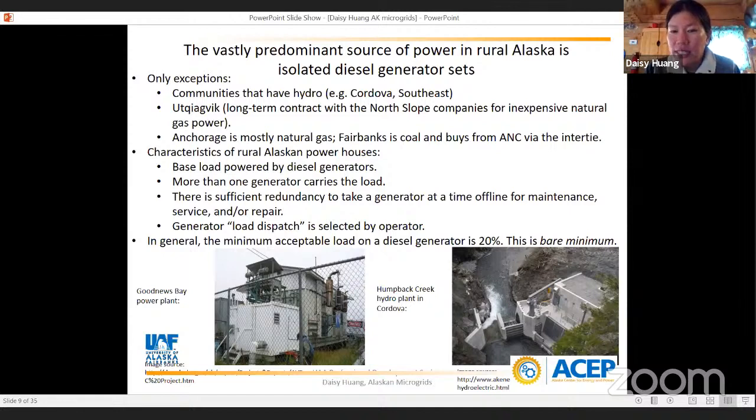Because on a sunny day in the middle of summer, when there's no rain forecast for the next week, you might think, oh, we can go all solar now. But you can't just turn off your diesel, because you never know when one cloud will go over your solar panel, and your diesel can't just spin up out of nowhere. It has to be running at its minimum, just flywheeling along at 20%. And that is just burning diesel for nothing. So again, balancing these things is hard.